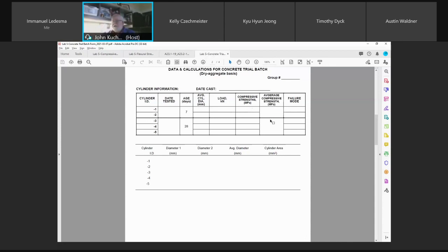That's what it is. There's nothing you can do to a concrete cylinder that's going to make it break higher. Once you cast a concrete cylinder, everything you do to it affects it in a way that may take away strength. So if one cylinder made 30, there's no reason why the other one at 22 didn't make 30. So it's legit. So you take the 30.